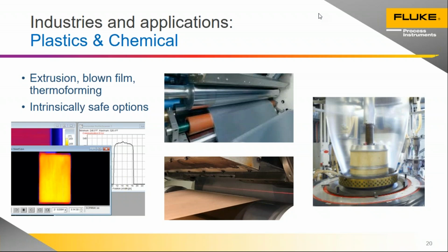Yeah, very often with line scanners and also with thermal imagers, if you're using those in a process, you usually have an HMI or a computer screen nearby the operation where the operator can really get a visual on that temperature profile as they're operating. Just from their experience with the process, they can tell what looks good and what looks bad pretty quickly.